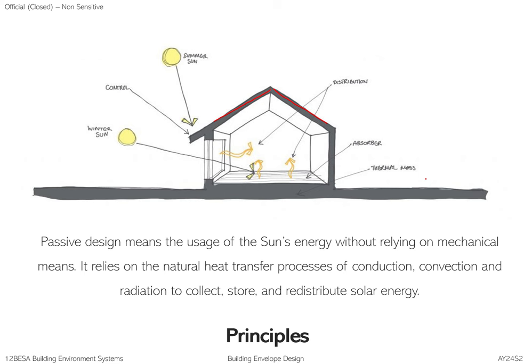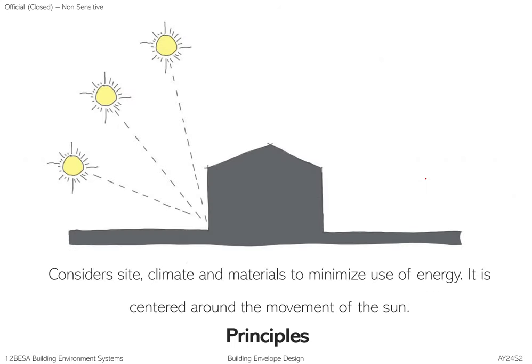So when winter comes, it's going to be very cold. Okay, so in that kind of situation, you would want as much sun as possible to penetrate deep into the space, and I want to collect it. I will want surfaces that are very absorbent of this energy from the sun, right? So it collects, and it radiates out in the interior space. So it reduces the reliance on artificial means of warming the space, using radiators and so on. Okay, so this is the basic principle behind it.